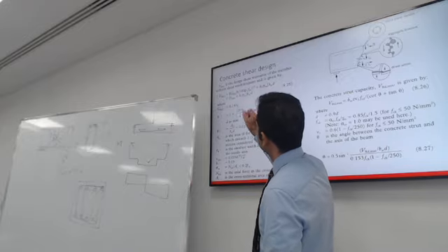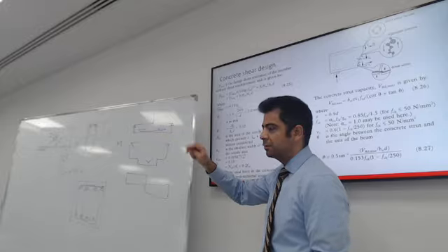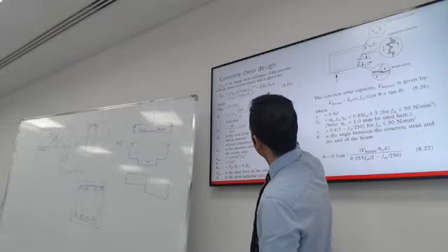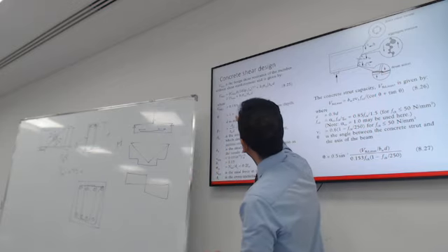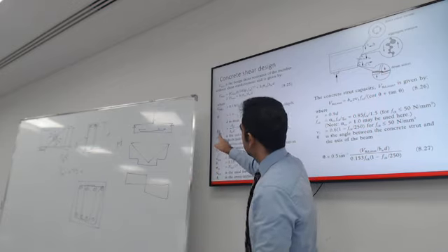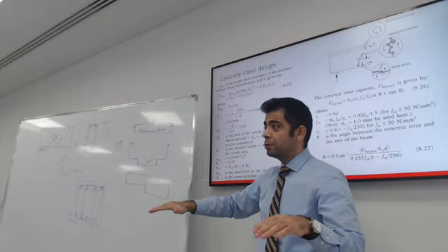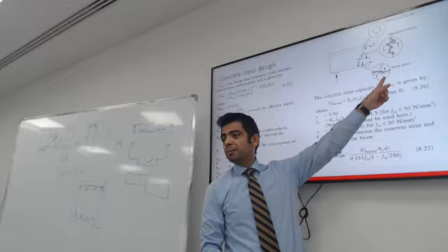Most of these symbols, you will realize, depend on pretty much two things. The geometry of the cross section, the width and depth. Rho 1, which is the reinforcement ratio of the longitudinal bars, because the longitudinal bars help with the dowel action.